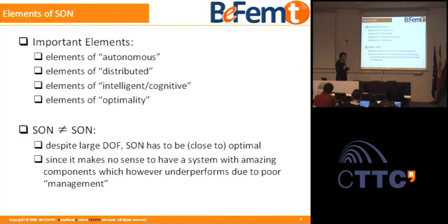Threshold-based decision means I'm going to hand over this user from this base station to that base station if the signal to interference noise ratio falls below a certain threshold. This is threshold-based decision taking. There's no intelligence in there. It's deterministic. If your algorithm just does, or your power does something really funny, your algorithm will fail.